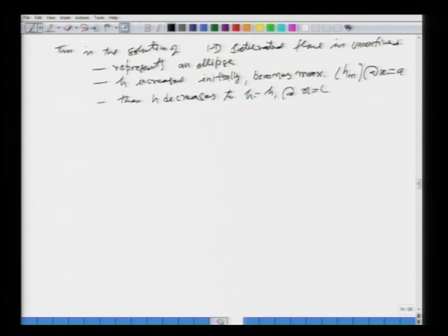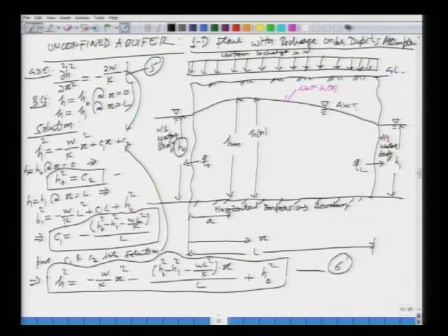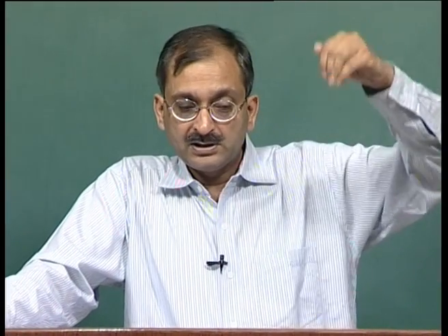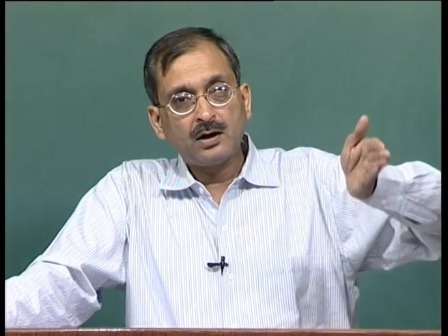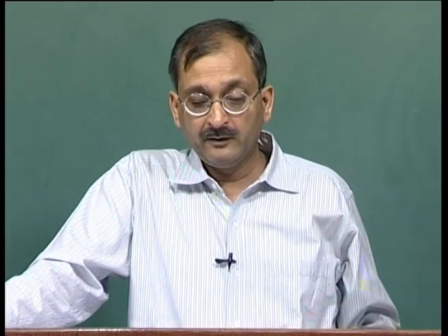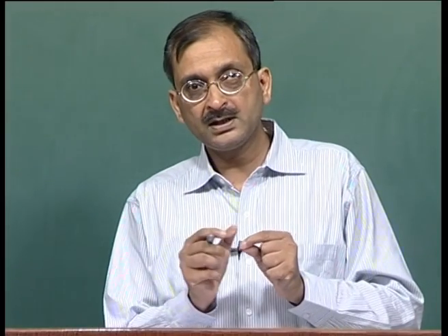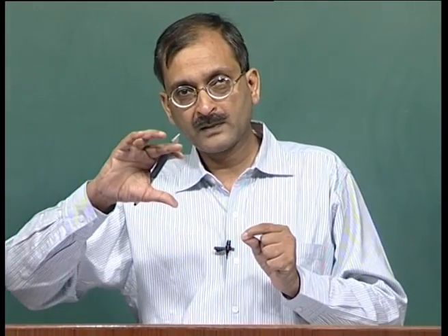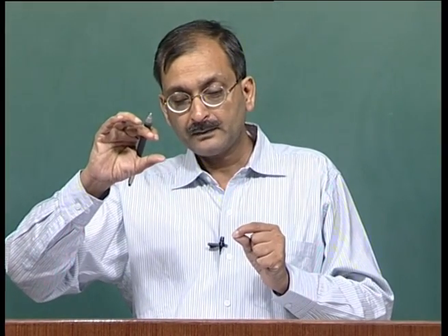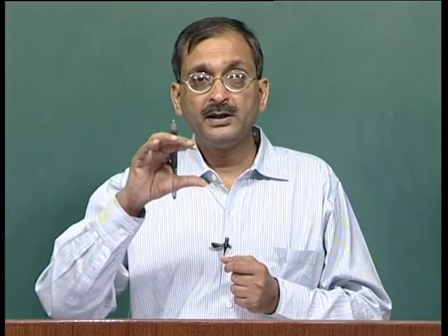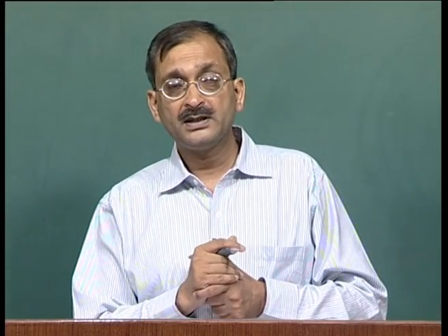Now, what is this h m? H m is the maximum groundwater table. Whenever we have an unconfined aquifer and there is a recharge taking place, we know that the groundwater table will rise somewhere in the middle. Finding the location of this maximum head, or the maximum groundwater table, and its value, h m, is extremely important.